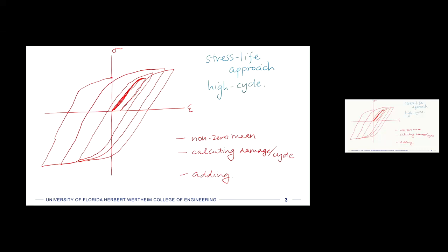And we've had to bring in some other concepts, because when we think about cracks forming and propagating, the stress life approach doesn't handle those very well. So that's why, when we did the damage accumulation, there was that double linear rule. So we sort of said conceptually these represent these different crack growth regimes.